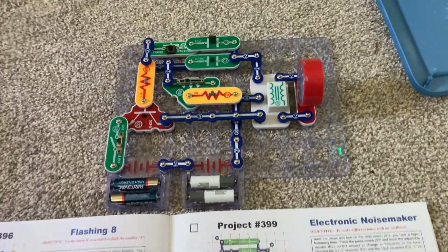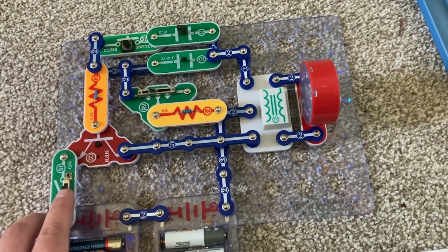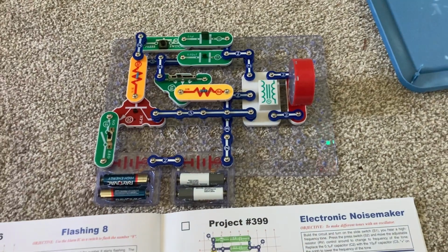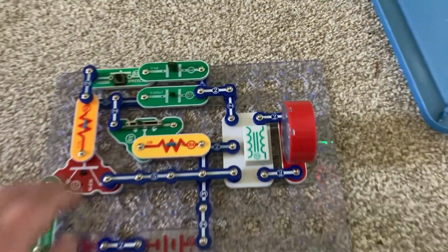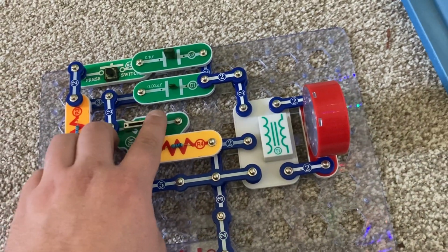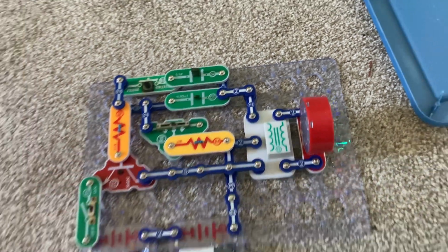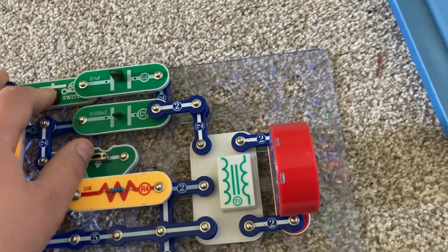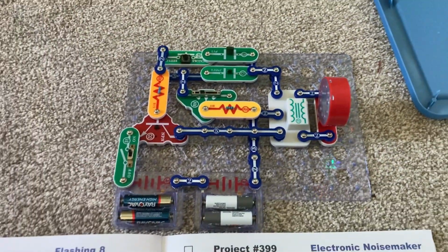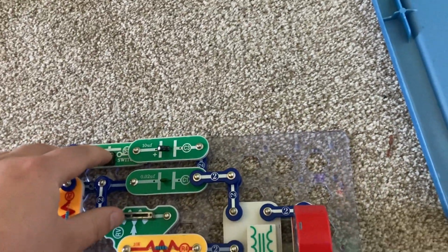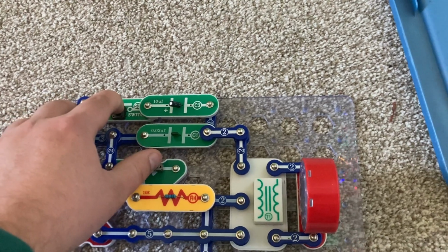This is an electronic noisemaker. When you turn on the slide switch, you hear a high frequency tone from the speaker. You can change the frequency of the sound by pushing and holding the press switch and moving the lever on the adjustable resistor. On some settings, you won't hear anything. You can lower the frequency of the tone by replacing the C2 capacitor with the C3 one and pushing the press switch, which includes the capacitor.